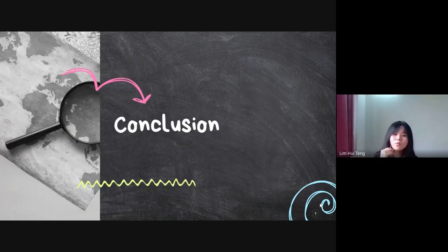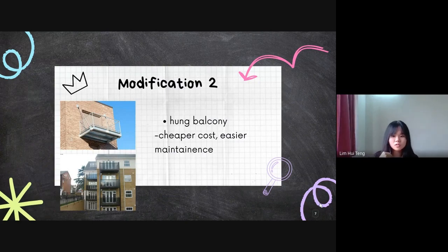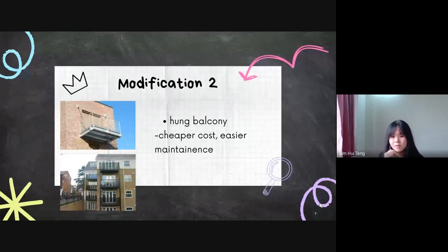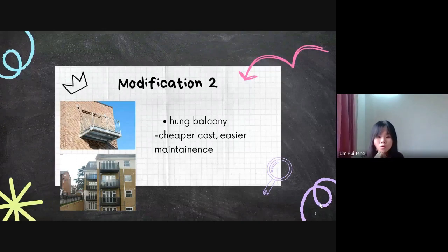But I disagree with what Jasin suggests, which is adding the 2 steel cables, because I think it is only useful for a small size balcony, and it is also for safety considerations only. But our balcony is big size, so it isn't suitable for us to use it. And I think we can modify our balcony by adding two additional vertical beams connected with three cross beams to support the balcony. So that's all from me.